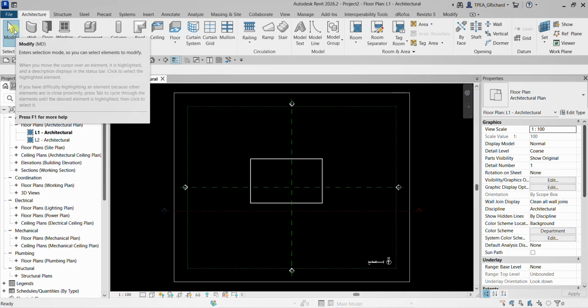What I'm going to do is convert this Revit model to an NWC file. I can actually open this Revit model in Navisworks directly, or append it or open it. It's just that the file size is too big if you open the Revit file, and it will take a few seconds. So what I'm going to do is convert this to NWC.